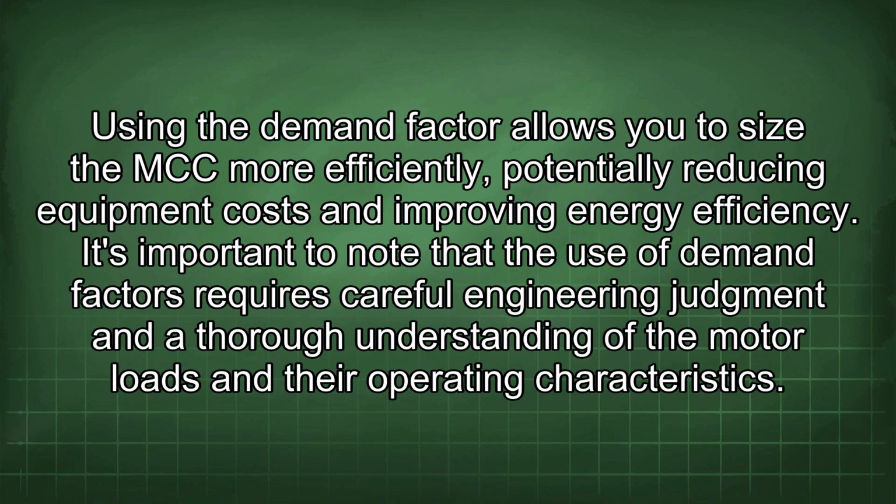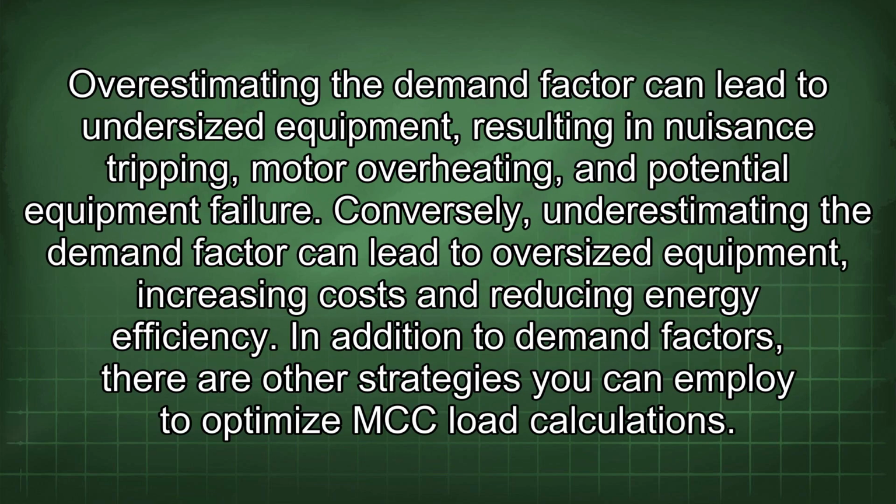Using the demand factor allows you to size the MCC more efficiently, potentially reducing equipment costs and improving energy efficiency. It's important to note that the use of demand factors requires careful engineering judgment and a thorough understanding of the motor loads and their operating characteristics. Overestimating the demand factor can lead to undersized equipment, resulting in nuisance tripping, motor overheating, and potential equipment failure. Conversely, underestimating the demand factor can lead to oversized equipment, increasing costs and reducing energy efficiency.